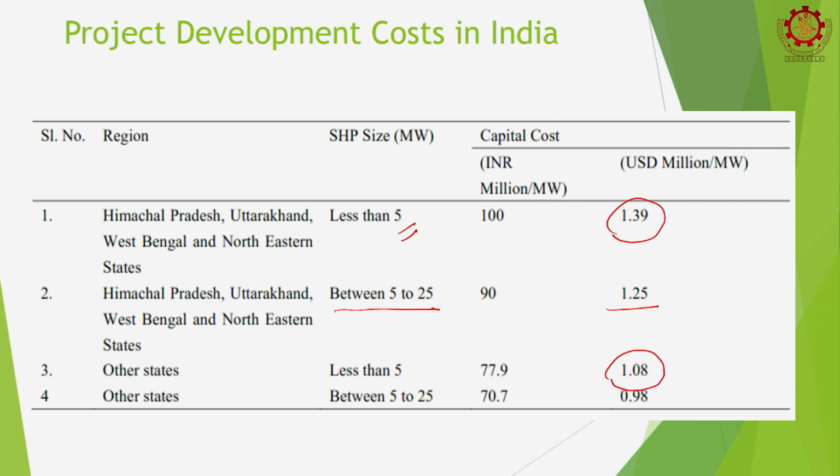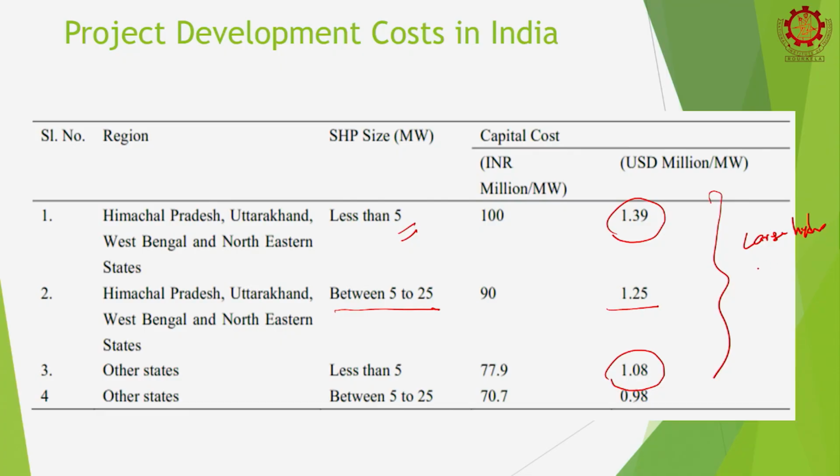But when it comes to large hydros, costs are much higher because there is a reservoir. Cost of the reservoir is huge. You have to have an expensive dam and a large extent of land to go underwater, and therefore compared to these things, I would say large hydros will go something like $3 million per megawatt, or even more, because there are a lot of costs for relocating people, building new houses for them, and there is a lot of involvement. So therefore, large hydros have much higher, we call them specific cost, per megawatt cost.